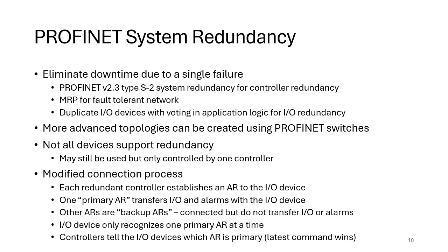So you could argue that that survives more different failures, because if a single cable is unplugged, then it will allow it to carry on. But we've already got MRP, so having that extra cable doesn't help because we've already got a fault tolerant ring. Now some people will do an analysis and say, well, R2 gives you an extra capability if an I/O device fails. And that is true if you've got simplex I/O.